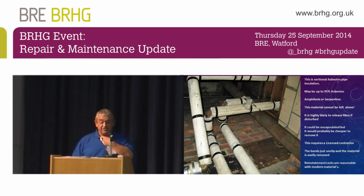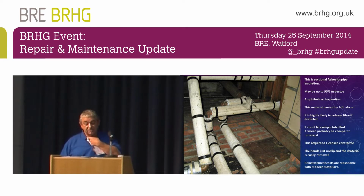Sectional asbestos pipe insulation can be amphibole or serpentine. This material cannot be left alone. It's really damaged. People are going in, accessing this riser quite a lot. It needs to be taken out. It's going to have a really high fibre release if someone bumps into it. It's pretty well damaged, a really nasty condition. It could be encapsulated, but that really is a waste of time. Risk assessment wise, this is easy to get out.